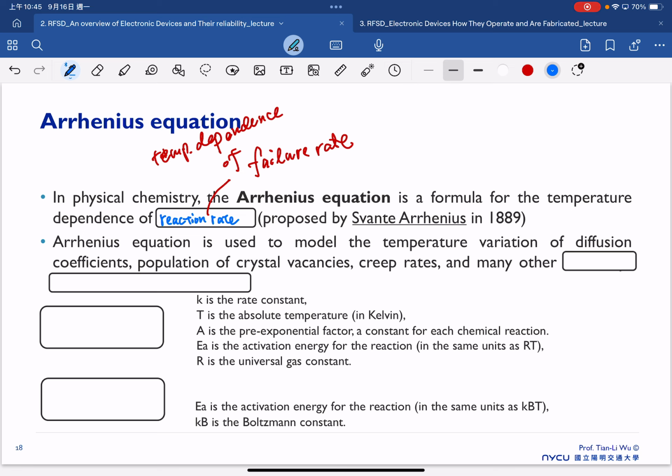As we already mentioned, if we do room temperature testing at VG of 5 volts, we probably need more than 5 years to see the device completely fail. Of course, 5 years is not a timeframe we can accept in the lab or in the company.